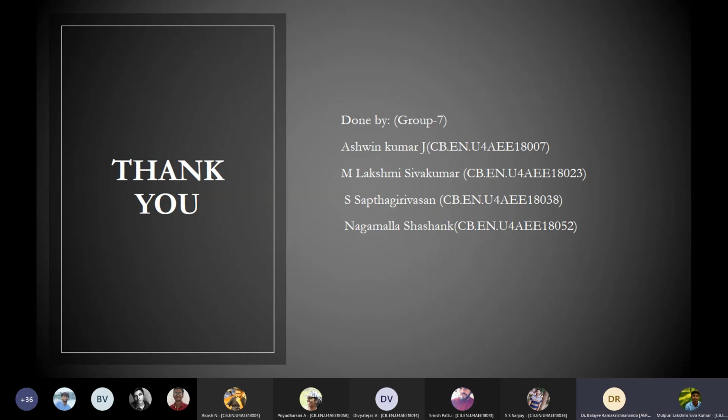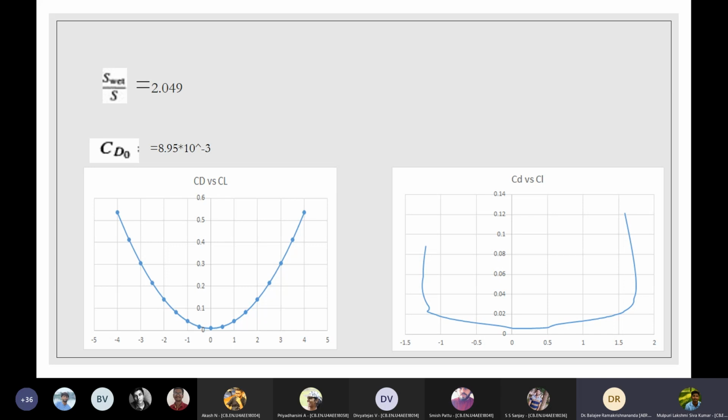You find the velocity, the free stream velocity. That is the easy way to do. Otherwise, you have a formula for lift using the Mach number also. Instead of half rho V squared, you use half gamma P M squared. But then what is P infinity? You have to find that in that case. If it is not there, convert this to velocity and find half rho V squared. For finding drag, I am telling.